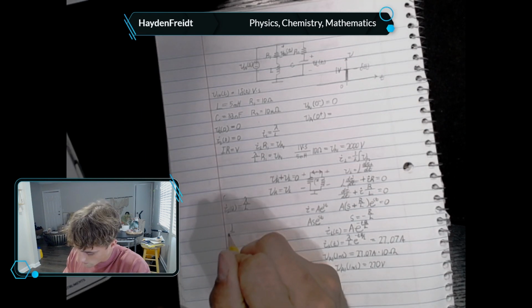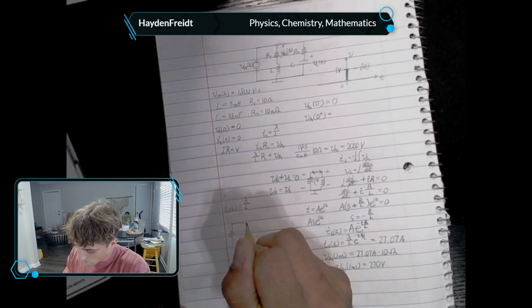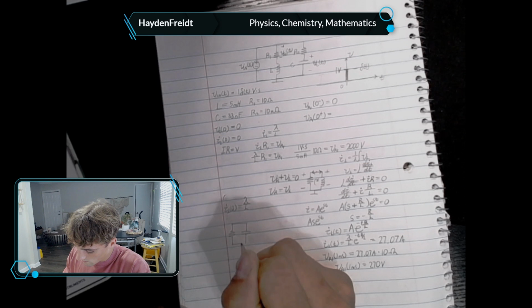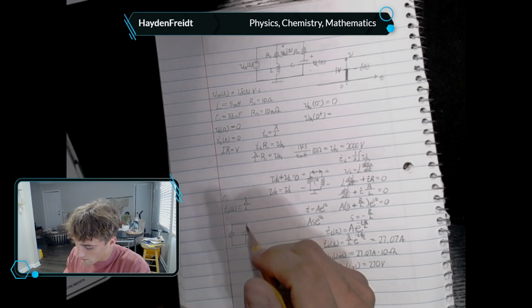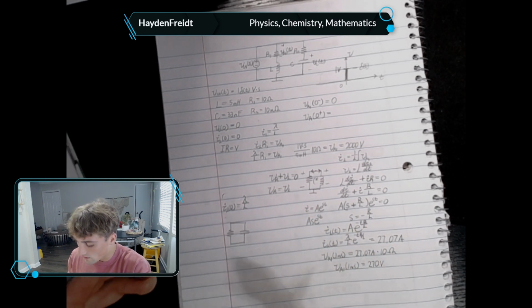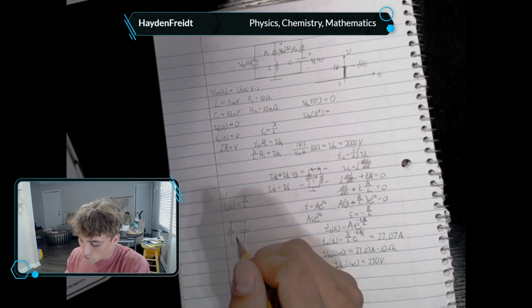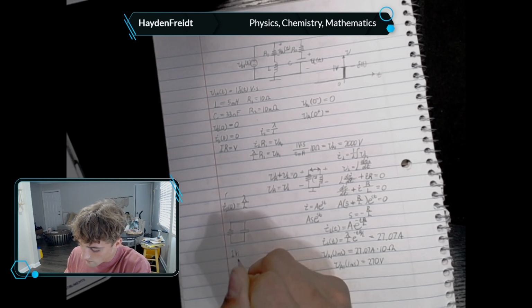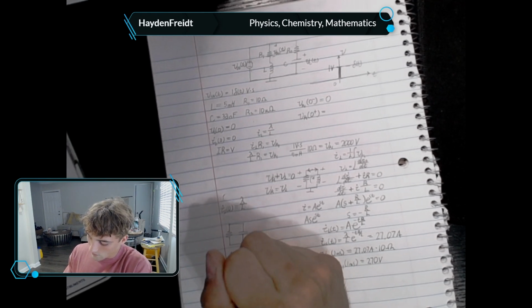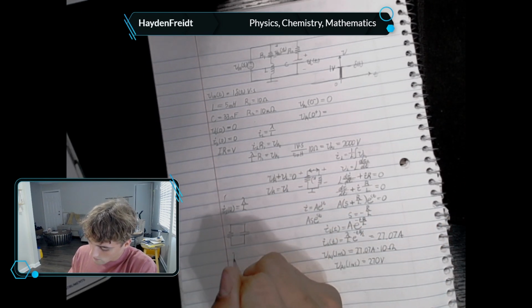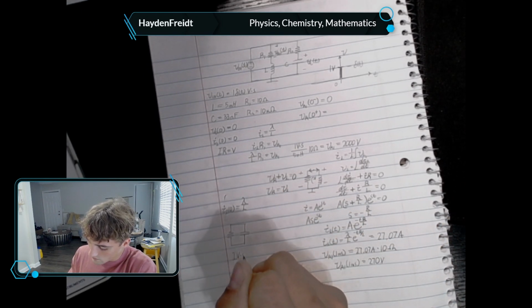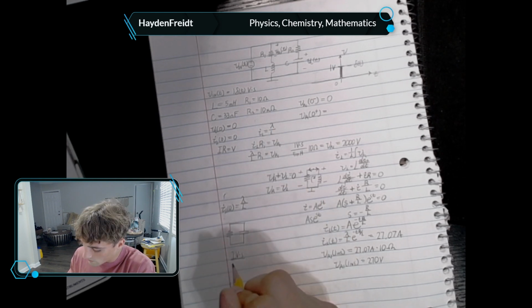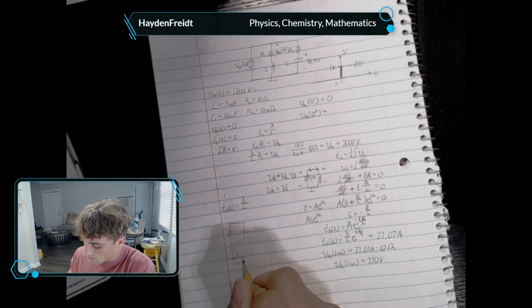It's just going to be a resistor in parallel with this capacitor. Now we have the application of the impulse. The capacitor is going to look like a short circuit. So if all the impulse falls over the resistor, we're going to have the impulse itself, which is 1 volt second. Here, I'll write that in a different way. 1 volt second, and then this is going to be divided by R2, which is 10 kilo ohms, which is 10,000 ohms.